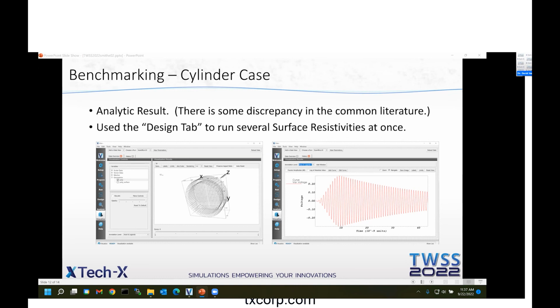And the size of the wires in the wall is about the skin depth at 60 hertz. But we do stuff at gigahertz here, and so our skin depths are not resolvable. Maybe I'll qualify that when we get up to terahertz, then we start worrying about skin depths again.